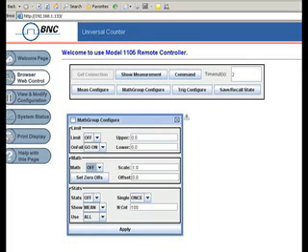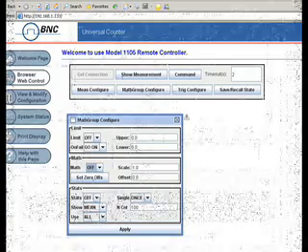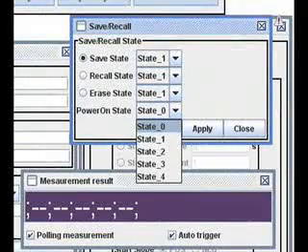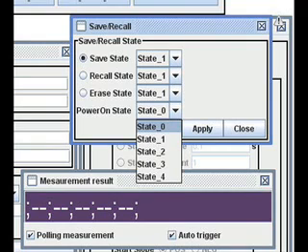Offset and scale controls allow scaling and offsetting the measurement results before they are displayed. Stats computes standard deviation, max, min, mean, and delta. Use all measurements, or use only those measurements within selected limits. N count selects the number of measurements made for each computed statistic. Single: one may also elect to take just one measurement.